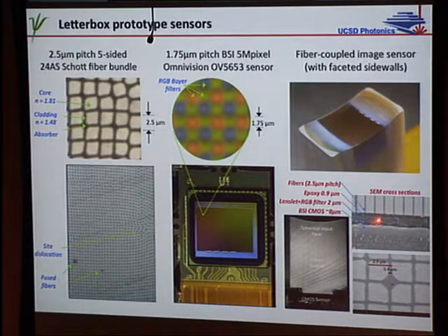And you can measure the glue line thickness very accurately, and it might amaze you that by this manually assembled part, we're getting a very uniform 0.9 micron glue line thickness between the fiber bundle and the surface of the sensor, which is, in fact, the lenslet and the Bayer filter underneath.